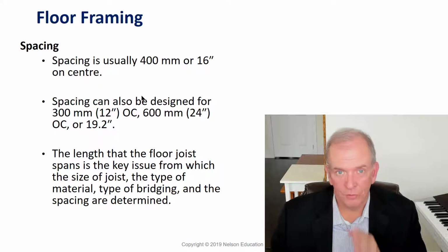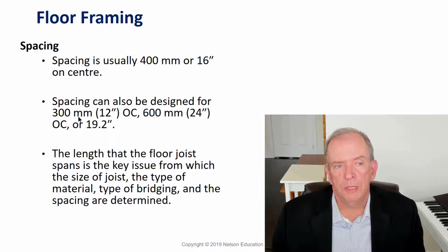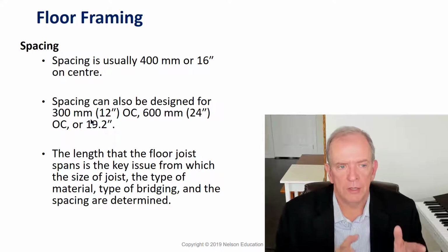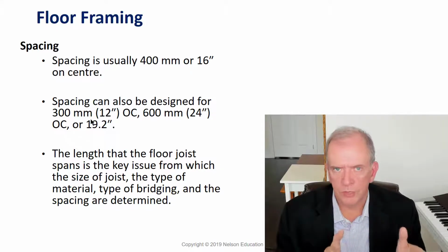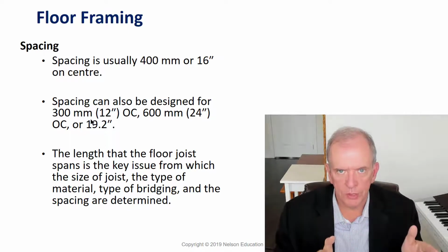That's just the conversion, and it's close, an even conversion. So 300 millimeters, I think, is about 11 7/8 inches, something like that. The building code will just say 300 millimeters. Nobody lays it out at 300 millimeters. Everyone lays it out at 12 inches or 24 or 16.